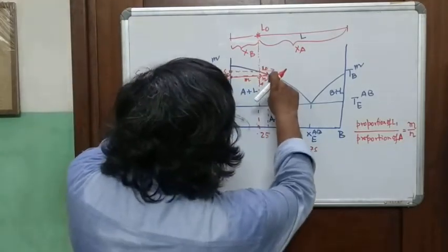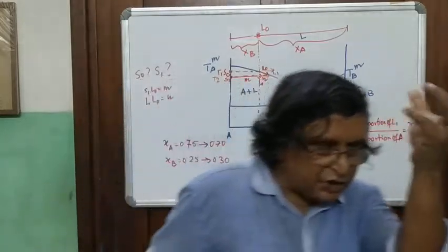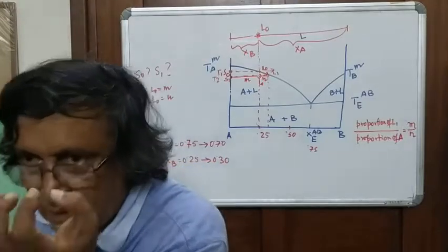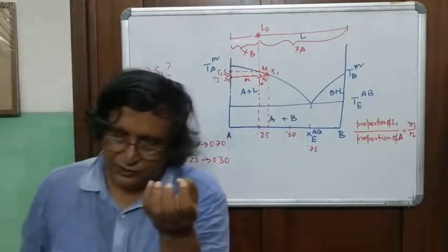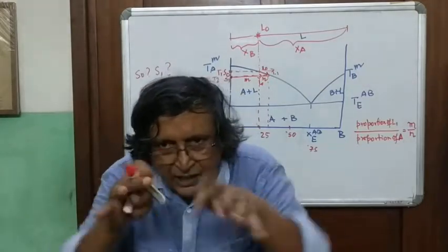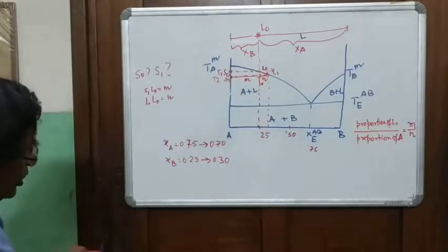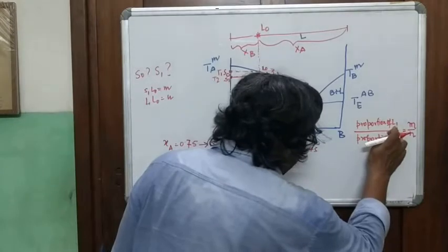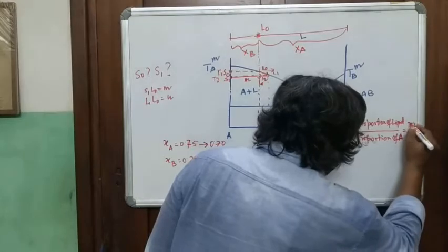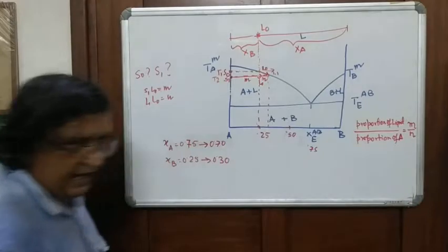Because the proportions of the solid and liquid will adjust such that the initial composition is not changed. So there is a mass balance. The total composition has to be conserved, and this will control the proportion of the liquid and the solid. The proportion of liquid is M at this point, and the proportion of solid A is N at this point.